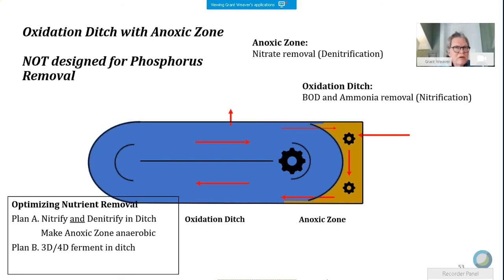And the bacteria that are settling in the sludge are the same bacteria that are in the mixed liquor, so they have an opportunity to chow down on those VFAs in septic conditions. And then when the rotor kicks back on, they're resuspended. Doesn't usually dial in your phosphorus removal as well, but it's certainly an opportunity.